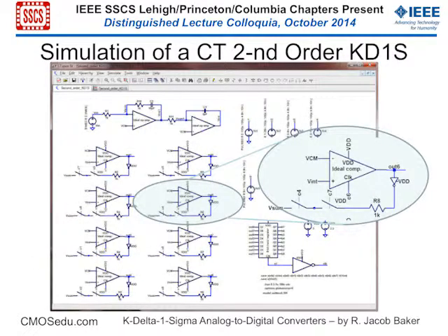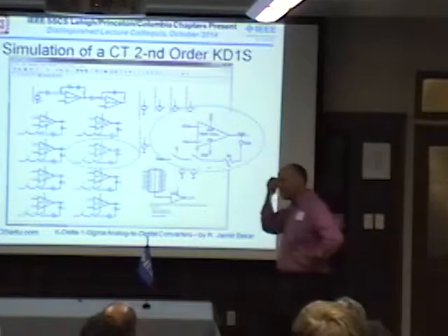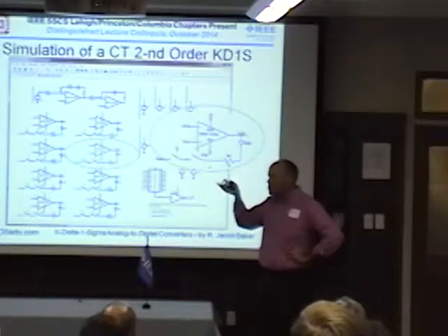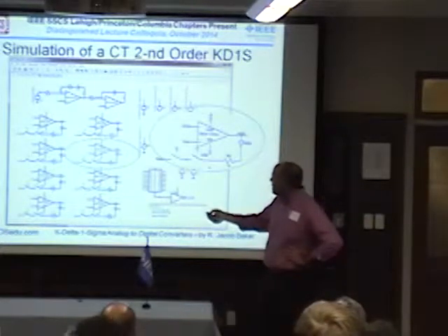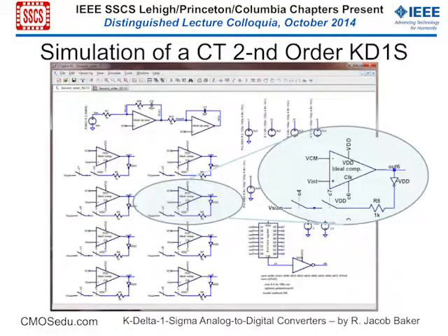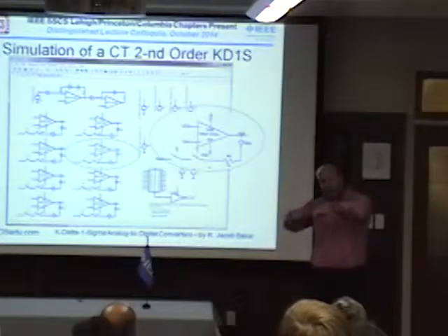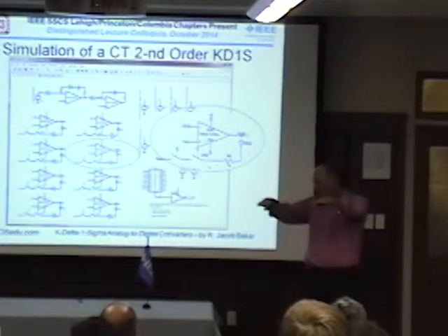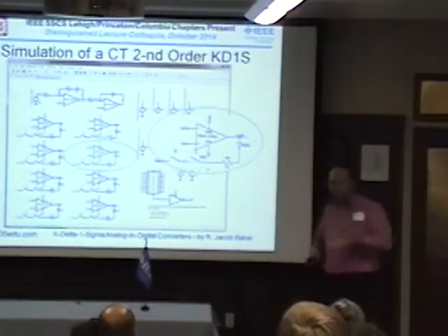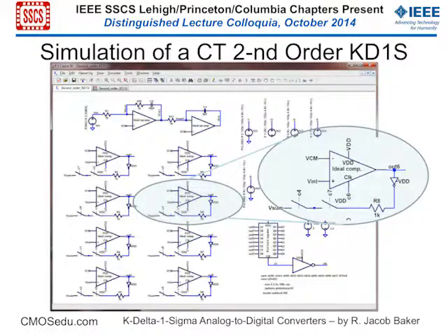And I did some other simulations using continuous time, because I thought, I did everything in switched capacitors, I wonder what would happen if you use continuous time techniques, which is where I was thinking of the application for the SerDes. Because you could actually take the resistors here and connect those to the input pad and have a little trim to adjust the 50 ohm input over all the frequencies, maybe 10 or 20% depending on matching. And then not have any switched capacitors and just have the clocks for the comparators that come in.